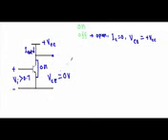So I can summarize this property. When the transistor is in on state, our collector and emitter terminal will get shorted, collector current will be equal to IC sat, and VCE, collector to emitter voltage, will be equal to 0 volt.